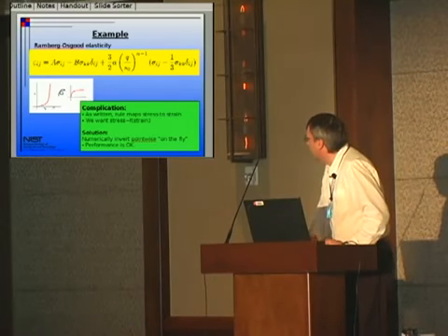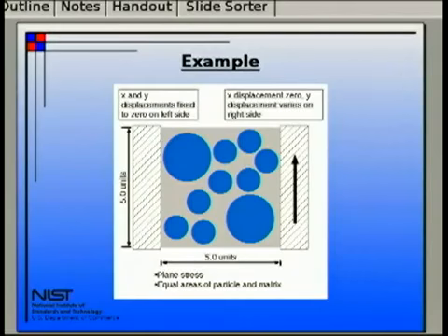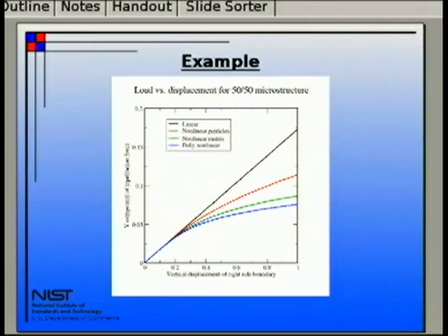And so I did put together a microstructure that does this, and this might be the hello world of material science, if you want to think about it this way. The point of this example partly is to illustrate the implementation of this Ramberg-Osgood plasticity rule, but also this is a microstructure where, obviously synthetic, I made this up, I did this in a drawing program, where the area fraction of the blue and the gray parts are the same. So if you had something that assessed this material as a function of area fraction, you would make a serious mistake.